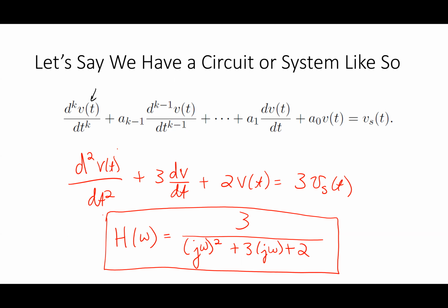And if you looked at what you did in 2112, you basically said, well, if I have a capacitor, I could say that the current is I equals C dV dt, or V equals I times 1 over j omega C, right? If you look at those relationships, you'll see that to get from this to this, I am applying basically this idea right here. The derivation of the impedance piece comes from this statement that I've got here.